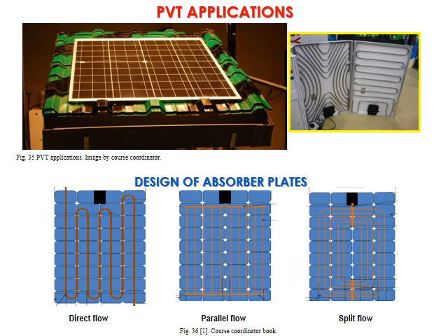This is our PV, okay, and this is the back of the PV. We put pipes in this way, as you can see, in this way, in this way. These are different types of collector: direct, parallel, split. The idea is we touch them to the back of the panel, to the cell, and it gets heated because the cell is already heated by the sun. Okay, we try to flow the water here to cool the back of the panel, so we cool the cells.